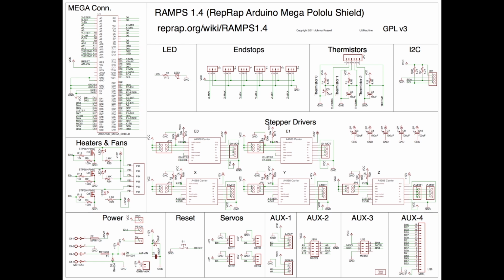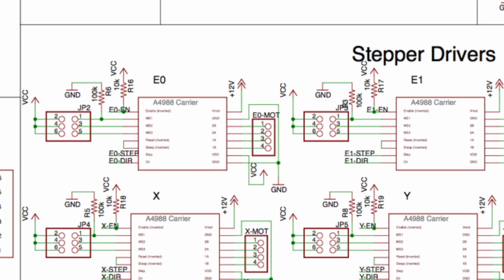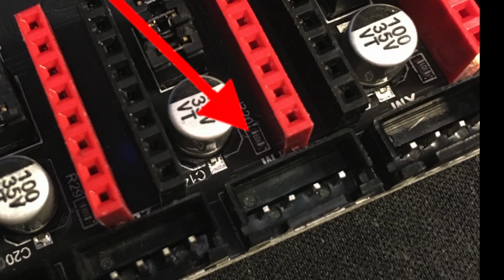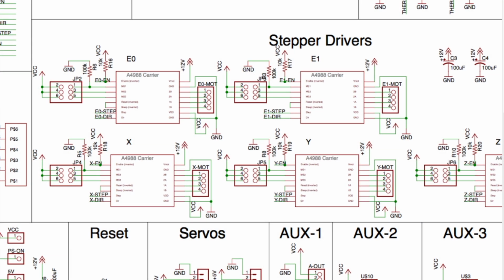Now, not even mentioning it indicates to me that you're just saying, oh, we're defaulting to the standard. Well, we don't really have a standard for that. You could say the standard is the RAMPS board. I guess that's the closest we have to a standardization for those jumpers. So do we just assume that MS1 has a pull-down resistor of a value of 100K? I mean, I see a 10K resistor right here, vaguely near the jumpers. But that's just another thing that we would have to take a ton of time to figure out, or at least some time, as opposed to just looking at a pretty picture of a schematic and figuring it out from there.